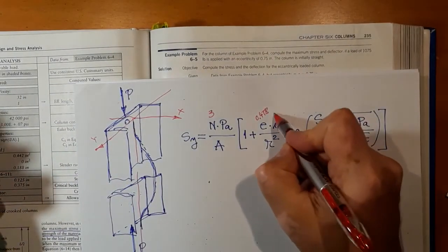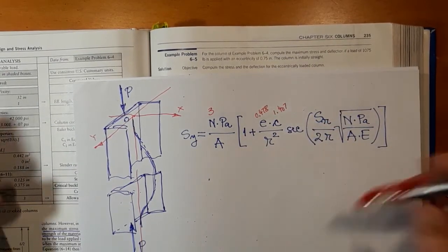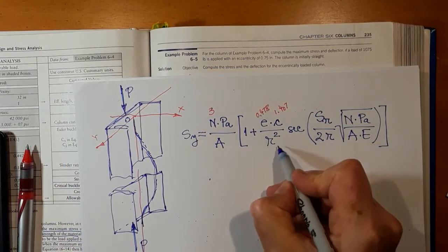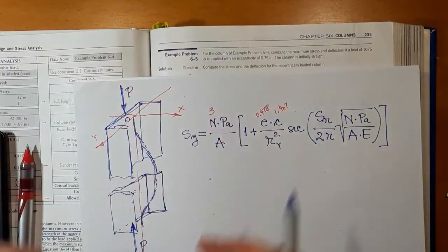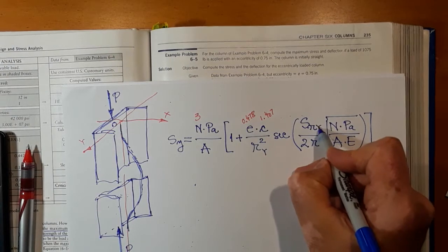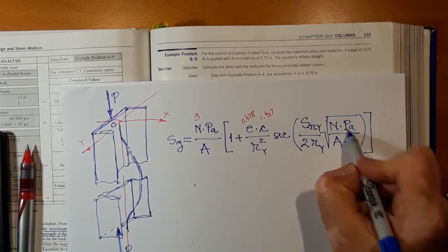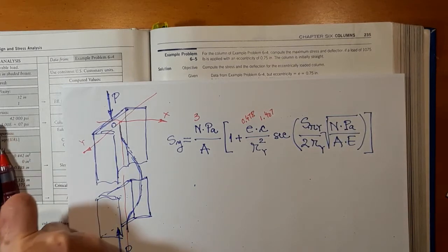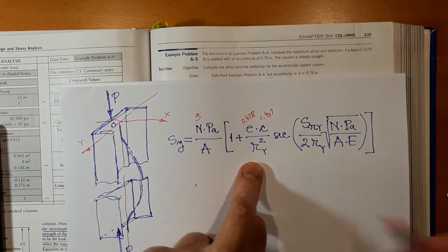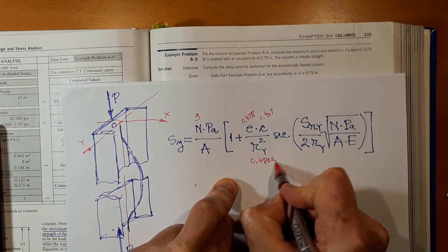Okay, so 1.407. R is going to be Ry, because buckling happens in the XZ plane. Slenderness ratio is going to be the Y version, R again here. Alright, so let's further make the equation explicit. So Ry was 0.4893.